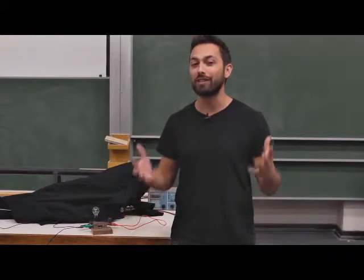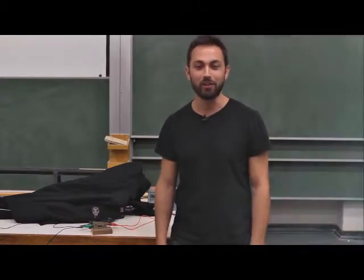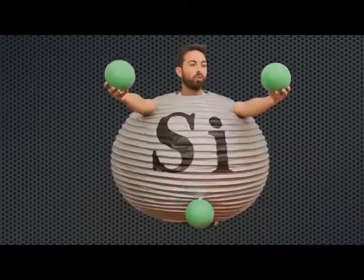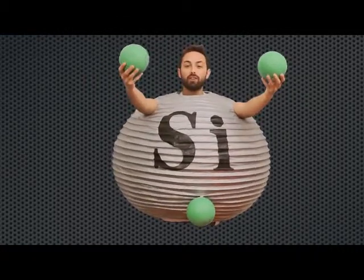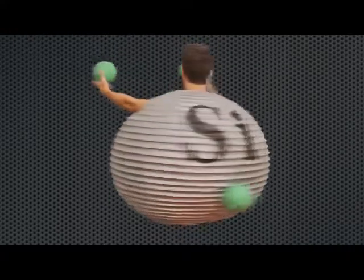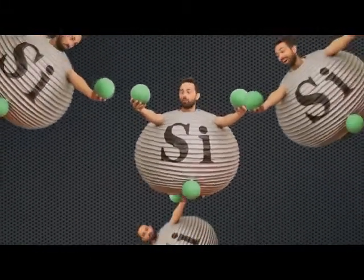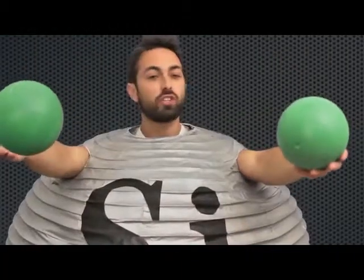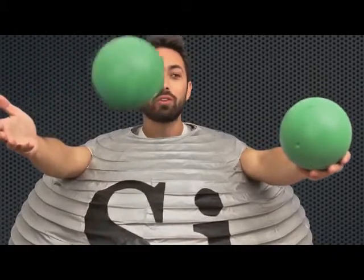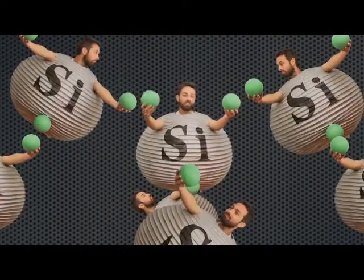Well, this is all thanks to the miracle of semiconductors. Or rather, I should say the science of semiconductors. Pure silicon is a semiconductor, which means it conducts electric current better than insulators, but not as well as metals. And this is because an atom of silicon has 4 electrons in its outermost or valence shell. And this allows it to form bonds with its 4 nearest neighbors. So it forms a tetrahedral crystal. But since all these electrons are stuck in bonds, few ever get enough energy to escape their bonds and travel through the lattice. So having a small number of mobile charges is what makes silicon a semiconductor.